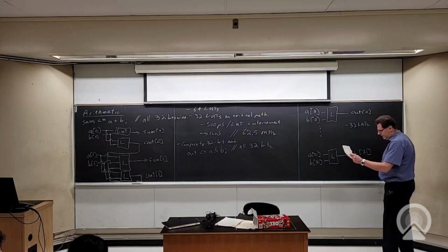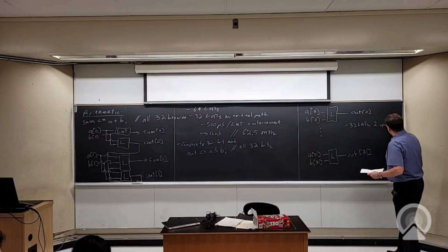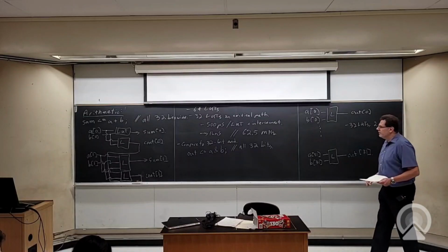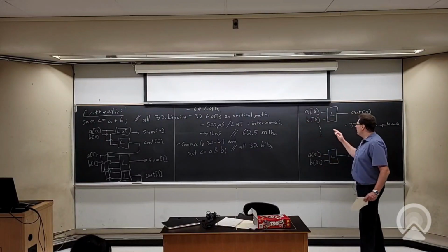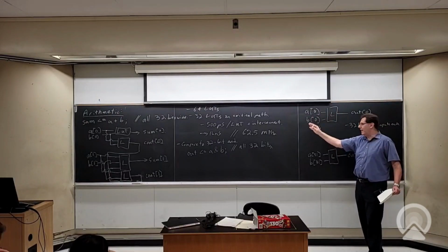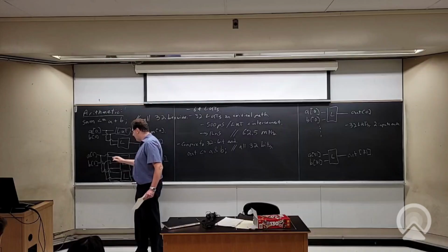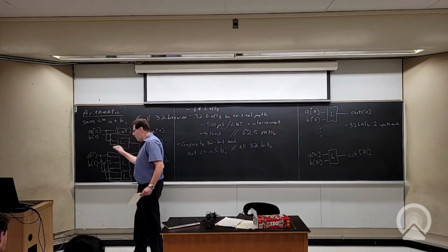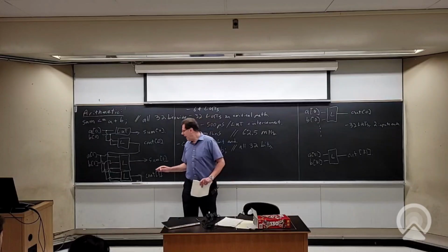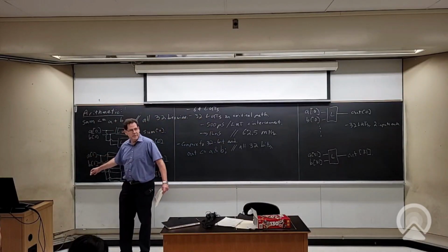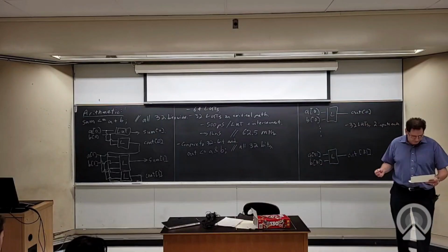Half as many LUTs, so that is better. They're 2 inputs each. Okay, so not fully used. It's a pretty good chance that I'm going to find some more logic to pack in with them. So if I've got ANDs, ORs and so on, this will all pack together pretty well. You could say, well, maybe you can find some stuff to pack into this too, but it's a lot harder, right? Like this structure is kind of more convoluted, this linear chain, and I am using 3 inputs for each of these LUTs. So I'm already using more of their inputs. I may be able to find some stuff that came from A and B here. So maybe I can pack some stuff in here, but I got more unused LUTs here. So the area is actually less than half.